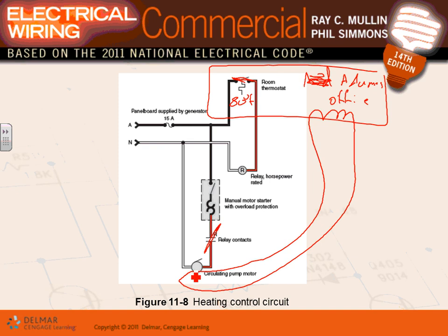And it radiates heat. Any comments, any questions how this works? So that thermostat in your room is controlling a circulating pump that's sitting somewhere else, and that pump has huge pipes that send the hot water to radiators. It radiates the heat into your area. Now you're cozy and warm. And then when you reach the set temperature, it shuts down. And of course, there's tolerance, like thermostats in dwellings, you have a tolerance in it. Very simple, very easy, guys.